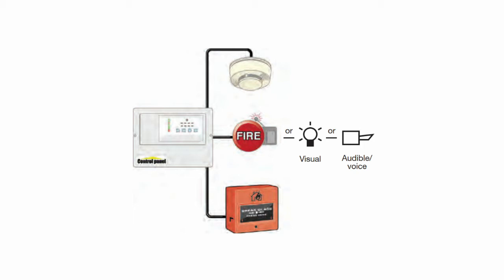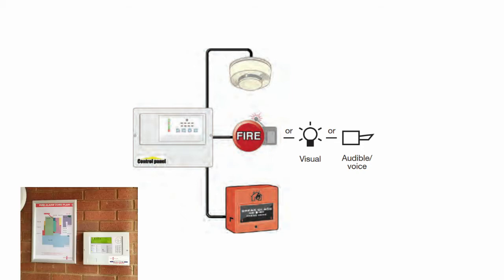Fire detection systems are further classified according to the way the information is sent and processed as either conventional systems or addressable systems. Addressable systems are more advanced, providing more control and the ability to locate the individual detector that triggered the alarm. Conventional systems only identify the zone the fire has been detected in. In order to help determine where a fire has been detected, a schematic plan showing fire alarm zones in a multi-zone system adjacent to the control panel can be useful.